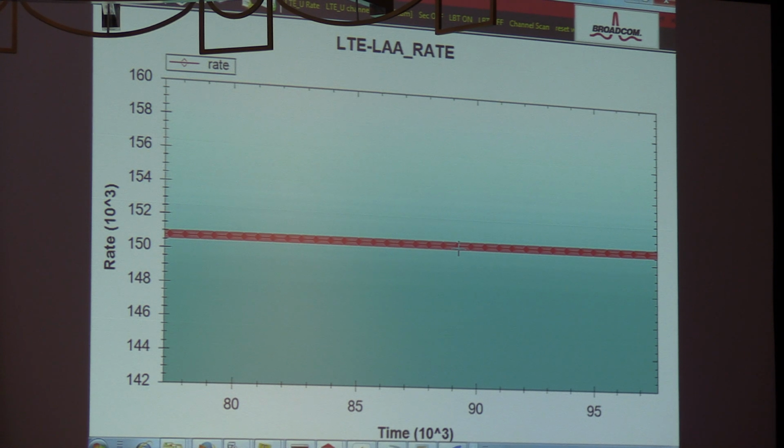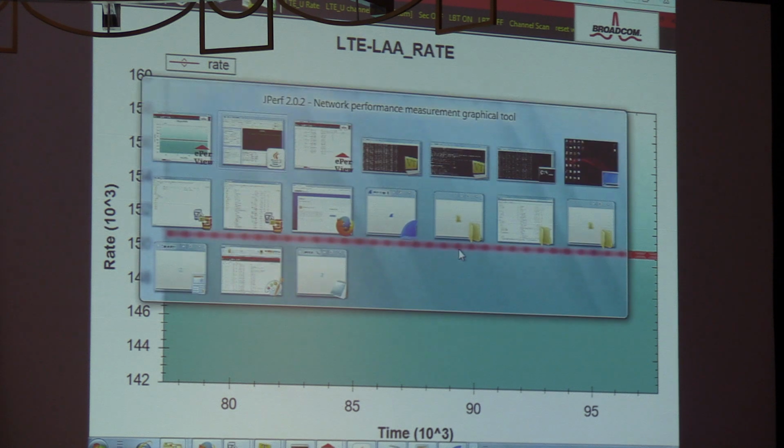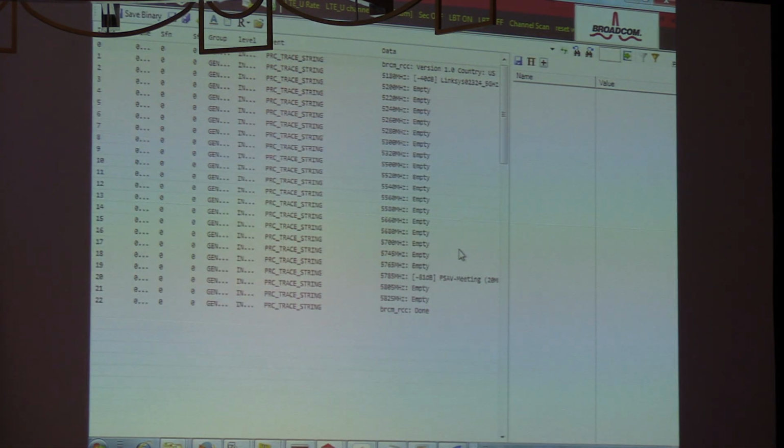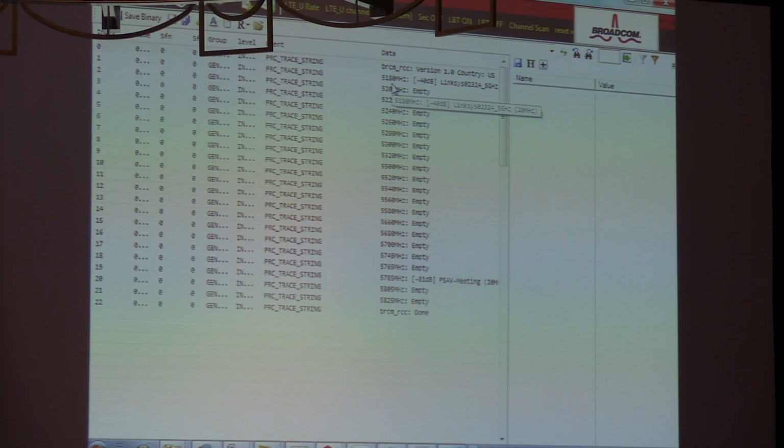So basically the first step, as Ilan mentioned, is the channel selection. We can see here in our debugging tool, it's called the Purview, the scan of the 5 gigahertz frequency. We can see the Linksys router, which is transmitting to the Samsung UE on channel 36, 5.18 gig.